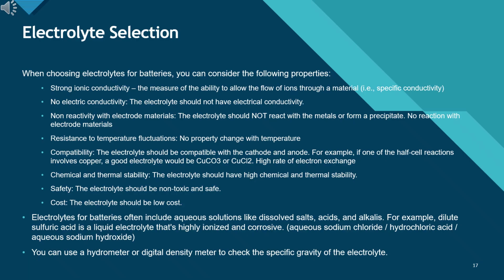Electrolyte selection. The electrolyte is the medium that allows ions to flow between electrodes. In a lithium-ion battery, this is commonly a lithium salt, such as LiPF6, dissolved in an organic solvent. The ideal electrolyte is a meticulous substance with a specific job. It must have high ionic conductivity to swiftly transport lithium ions from anode to cathode, while simultaneously having virtually no electrical conductivity to prevent a short circuit.